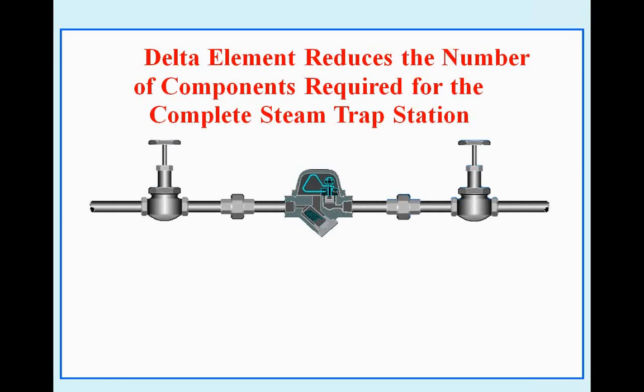Or a lot of people, although it's not a proper piping practice, will have two condensate lines of different pressure going into the same return line. Well, one's going to slow down the flow through the other. If you have one draining at 10 psi and another at 20, you're going to have issues. And we'll hear, hey, we're getting backflow through a trap in a given application. Well, a check valve will help that, but again, that's a piping issue. You always want to have the same condensate pressures on your return lines. But again, the idea here is having all the components in there, and there are technologies out there that have all those components in one type of trap.